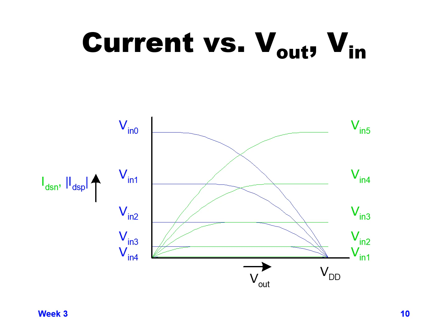But if VN is 1, you have a fairly low gate to source voltage. You're going to be in saturation most of the time, but you have a flat line pretty close to 0 current. Depends on what your threshold is. If your threshold voltage was 0.8 or 0.9 volts, VN 1 is just barely turning it on, and so that's why the curve is so close to ground there.